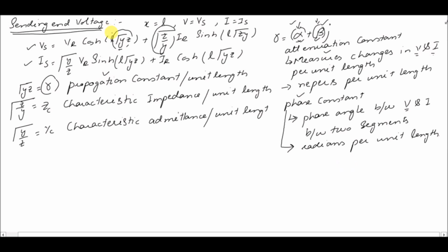Now we have a length term here as well as here. So we can write that L under root yz is equal to under root Ly times Lz, and this will be equal to under root capital Y capital Z. So this is the admittance of the whole line, this is the impedance of the whole line, and this is the length of the line.